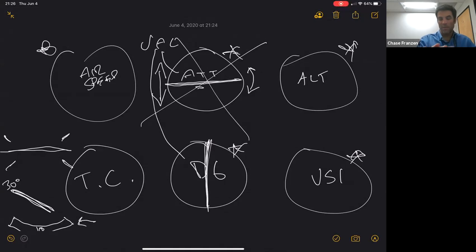If it's not centered, that's what I was trying to explain with the tail moving too fast or too slow for the rate, for the bank angle that you're in the turn. In different lessons we would have covered adverse yaw, and the nature of aerodynamics in a turn. But this is your indication of a slip or a skid. Again, the idea is that one of your butt cheeks is feeling more pressure than the other. Ideally, as your plane is banked in a turn, you should have equal pressure. I see. Okay, I think it's for another lesson, but it definitely helps us become better pilots. Yep, if we keep an eye on that instrument, right?